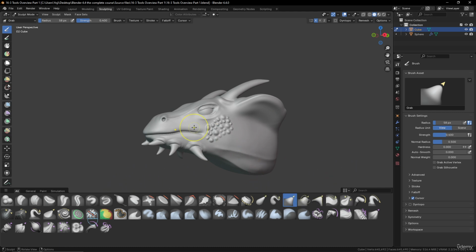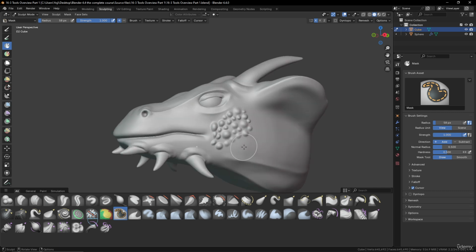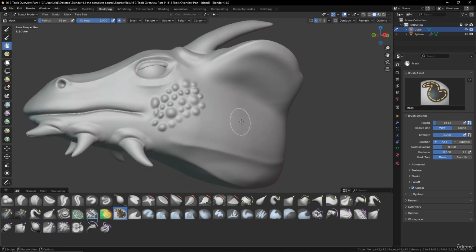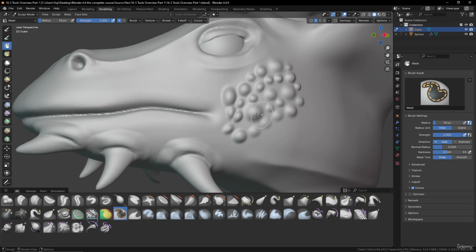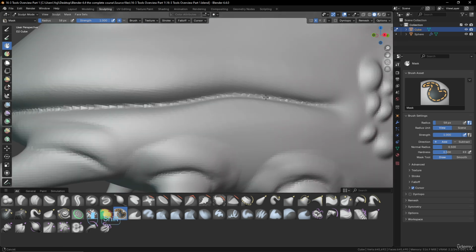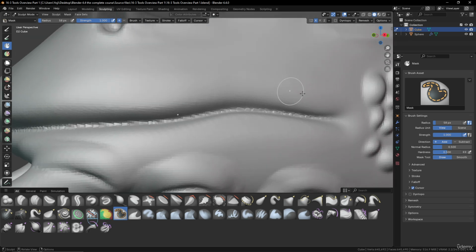The first one that is very, very important and not exotic at all, and that you will use very often, is the mask tool. So the mask tool is a very powerful one. If you want to play with specific shapes and add little details, like for example, let's say we would like to add maybe shapes like that into our lips over there. Okay, so let's go here and draw simple shapes like this, okay, that we don't want to be influenced by the sculpting.